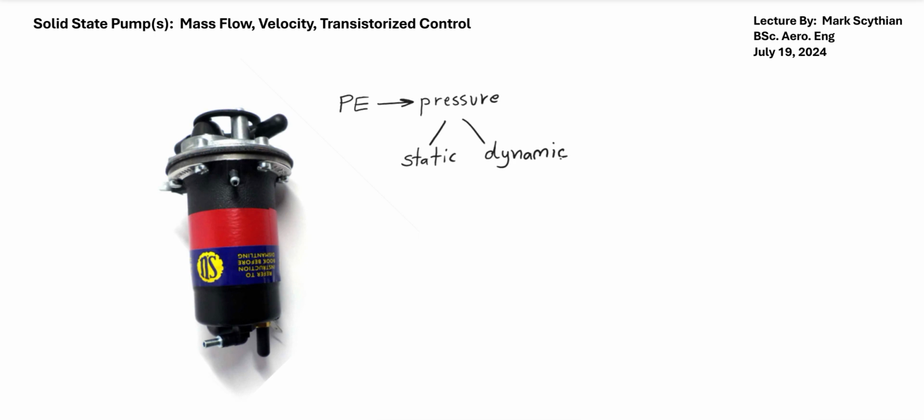obviously the pressure involved with motion, we could also equate it to a dynamic force of pressure times a cross-sectional area. But we do have a certain viscous resistance, not just correlating with the fluid density, the rho factor, but also with the geometry of the pump and specified backing pressure design parameters, which then stabilize a level of inherent static pressure. In other words, there's only so much fluid, gas or liquid, that can move through a channel, and everything else would be a level of static pressure.